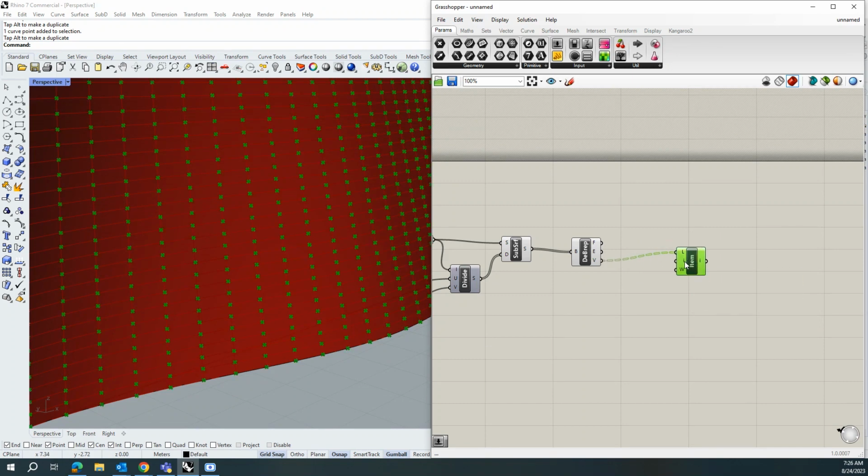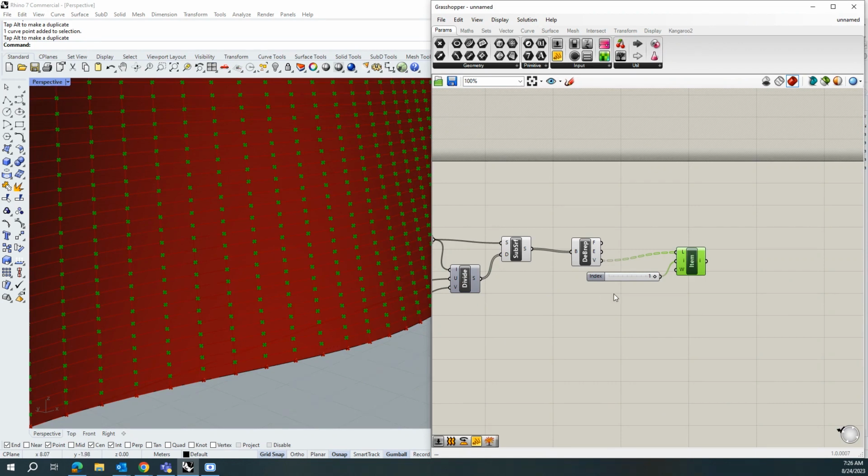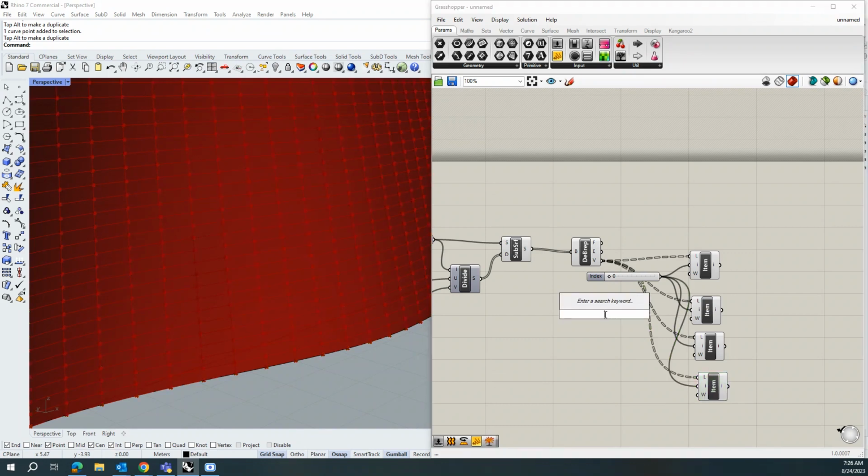By default, whatever the index value is, it is 0, right? That will show that point. If your index value is 1, it will select point 1. See, this is selecting this one. So I'll give this 0. I'll take a copy of this one more time, and one more time, because we have 4 points on the one surface, right? So 4 times I'll be taking a copy, and I will add the index for each of these components.